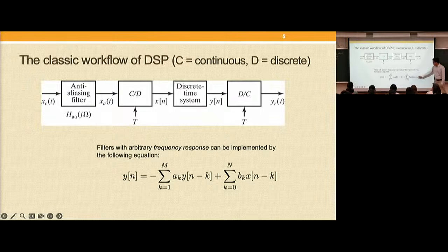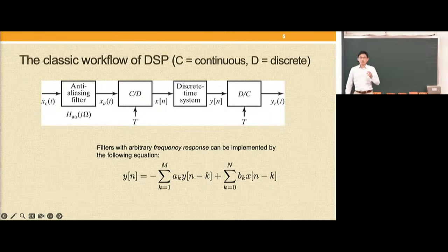And then there's another term which looks at the output the system already produces. We're also going to look at the output the system just produced over the m samples in the past, and then sum them all up. And then the result is the output for the current sample. It's what we need to compute and produce for the current time. So this is called a difference equation.